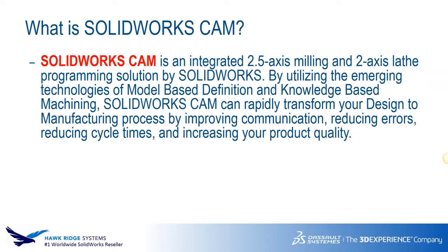And SOLIDWORKS CAM can leverage that information, access the tolerances, and use those tolerances to determine strategies on how to machine certain items. And also the knowledge-based machining, which is basically a way of saving your strategies, how you want to machine your parts and features, to a database so you can reuse them, so you don't have to reprogram things every time.